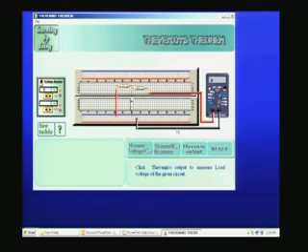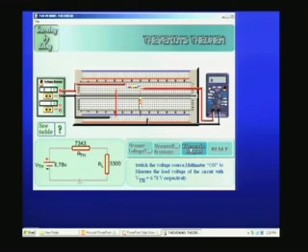Now we have to go and measure what is the Thevenin's output across the load. So the circuit now is simplified. You can see the voltage is connected here, and there is only this 7343, that is the Thevenin's resistance. This is the Thevenin's voltage source. Now we will have to set it for 6.78 volts, and this is the load resistance 3.3 K. Now we will switch on the power supply source, and then you will increment.